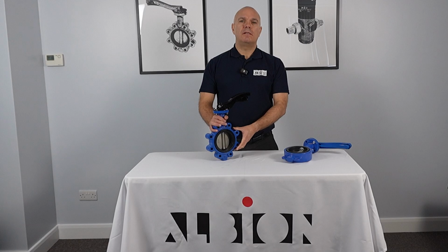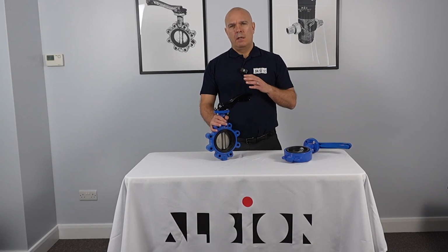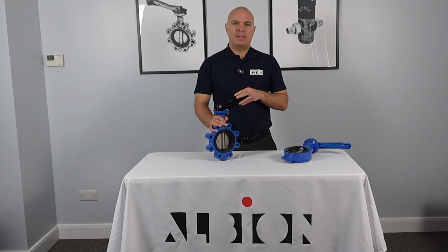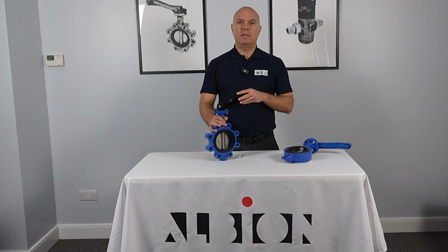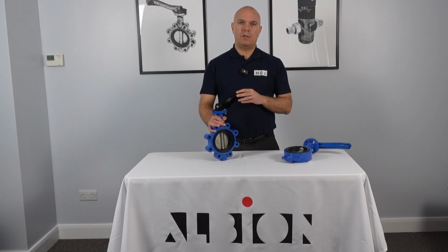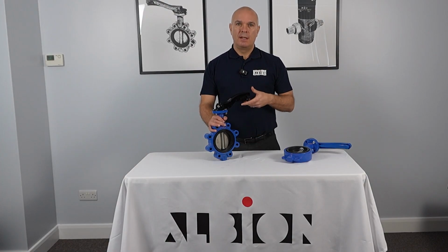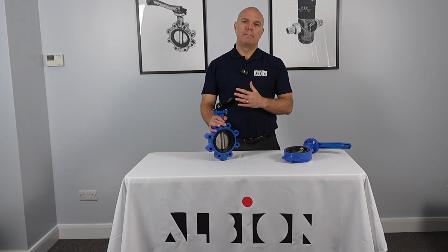A valve lever, in terms of the operation of a butterfly valve, is reasonably simple. It's a 90-degree rotation around an axis that takes place by applying a torque to the lever. By opening and closing the valve in this way, it allows the media to flow fully, have the flow regulated, or make the flow stop. One of the most interesting things regarding the design of butterfly valves, and as I briefly mentioned earlier, is that they can regulate the flow by opening the disc at a given angle between 0 degrees and 90 degrees.